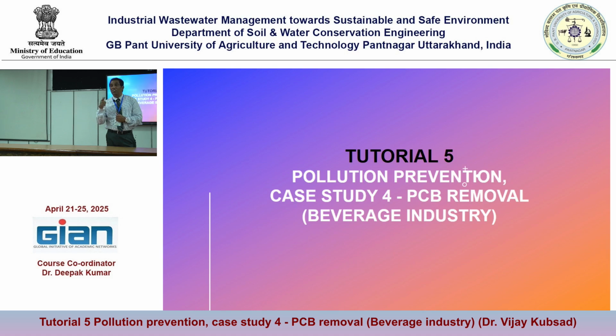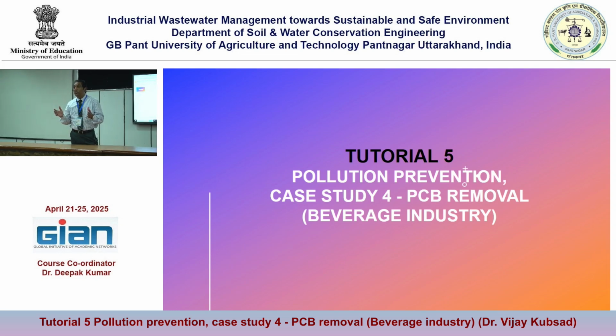TDS concentration is high. It gives rise to a different issue. If the TDS concentration is high, what happens? It enters the underground reservoir. There is a limitation where you want to dispose of it. You have to remove TDS. That's why we adopt the reverse osmosis process. What is our target component? The target compound is the TDS. We remove TDS.